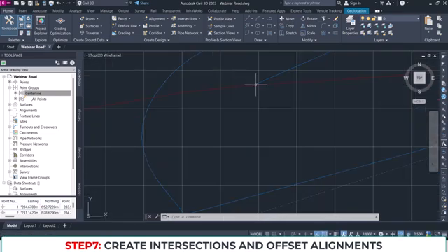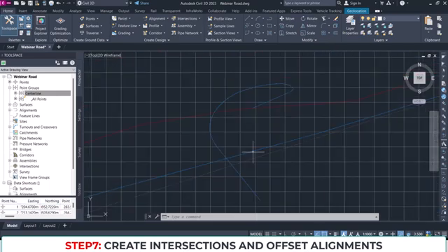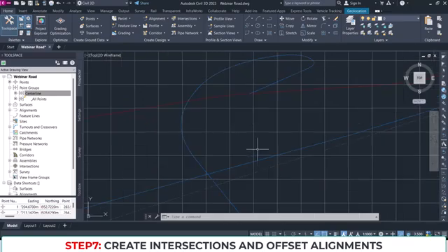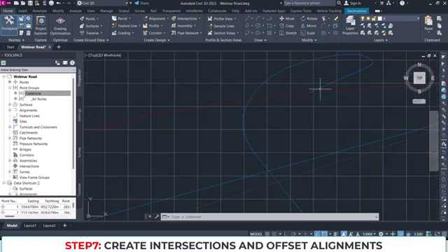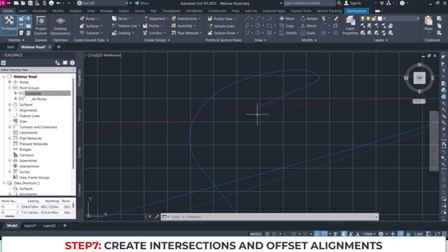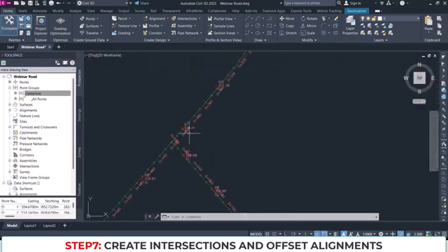These two blue lines, this is where the starting point is. So this one has to marry with this. But how do I do that? I cannot just drag it. I have to create an intersection. So watch this closely. By the time I create an intersection, these two will join. This one has to go there. Since this one is the one intersecting, it has to go down to meet this road. And if I want to adjust it back up, I have to adjust road 1 up, and then road 2 automatically follows.